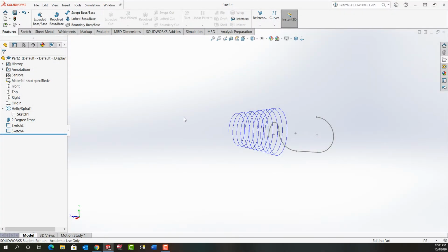In this video I'm going to demonstrate how to create the parallel plane in the geometry at this end of our spring. So I want to make a plane parallel to this. So I'm going to pre-select it, hold Control, and select this endpoint of my spring. So I'm going to make a parallel plane that pierces that point.